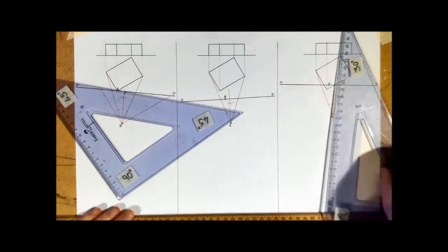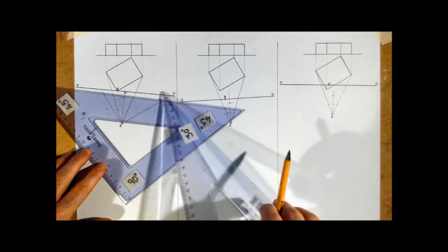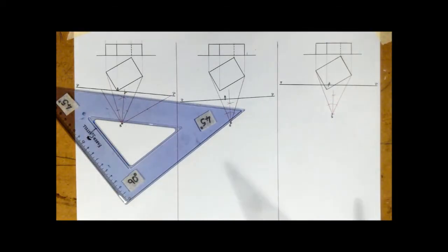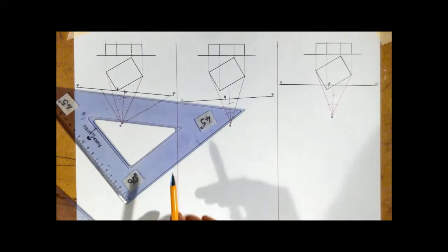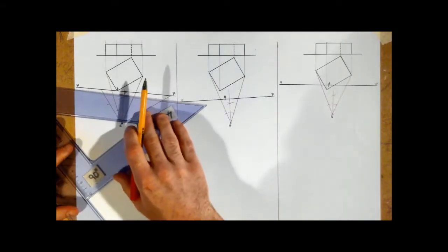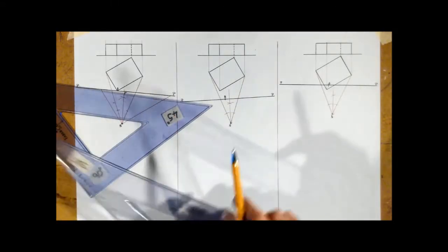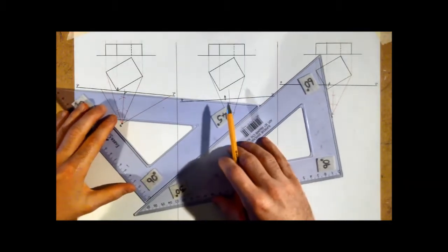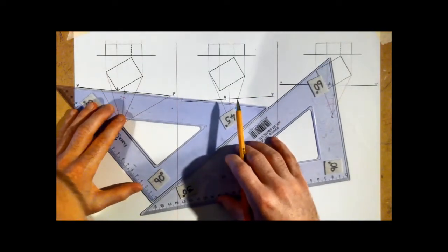Okay, so first of all, whatever way your picture plane came out, the ground line and horizon line are going to be exactly parallel to that. So what we're going to do is just a little bit of sliding set squares. So set up on your picture plane. I usually do the 45.